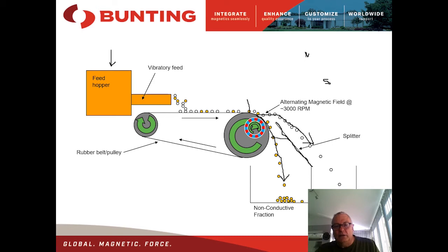Again, it's very counterproductive to have particles that are bouncing or quite ballistic in nature as they go into the field, because that means you're not going to get a settled separation and can get misplaced particles. Sometimes we can have a belt cleaner system on here if the client wishes to clean the belt prior to coming back into the feed area again.